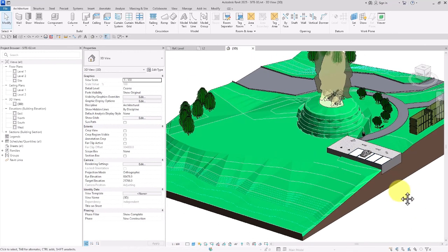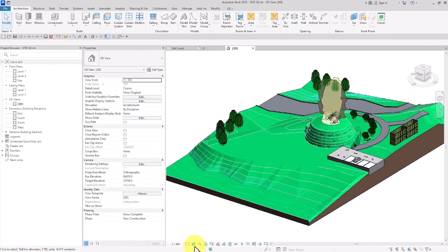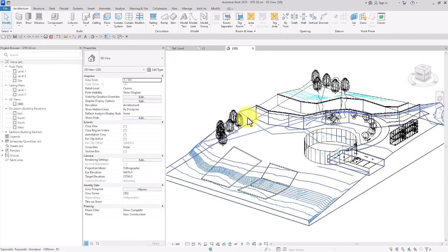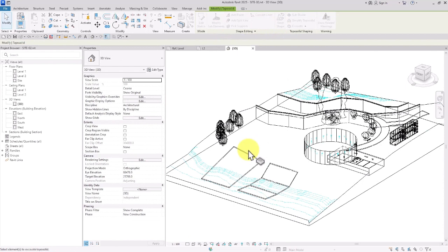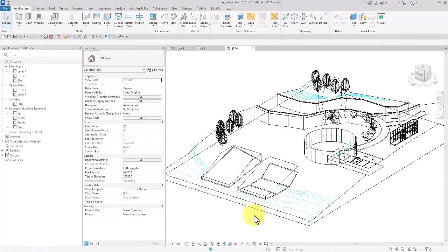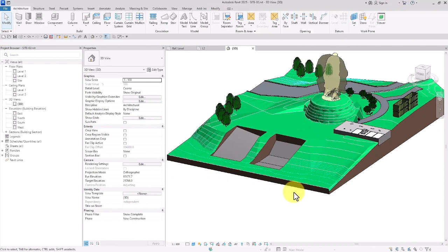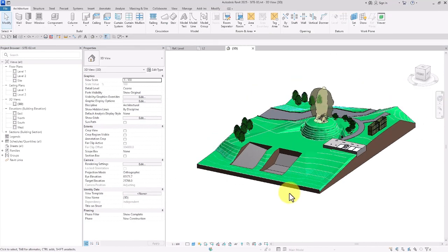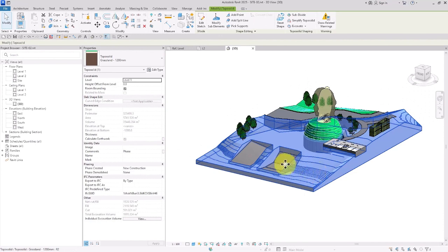Now let's talk about another interesting point. Let me just set this on wireframe and select these areas because we have used Ctrl Z before. Alright. An interesting point here is that when we use excavate, it's kind of like we have excavated the earth, right? I mean, in other words, it's kind of like we have subtracted soil out of an area. So, in Properties window down here, we can actually check the details of our excavation, such as the cut volume or the filling volume, and so on. And these numbers are quite accurate as well.